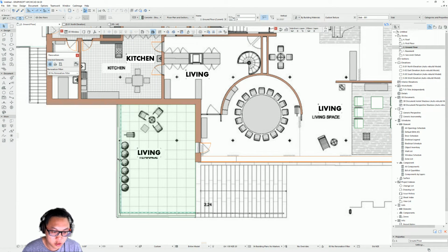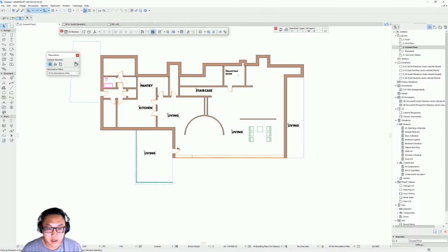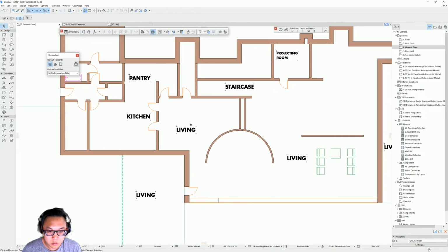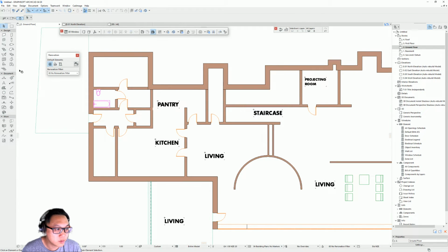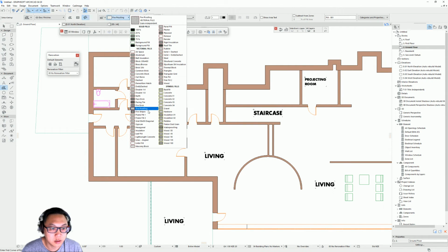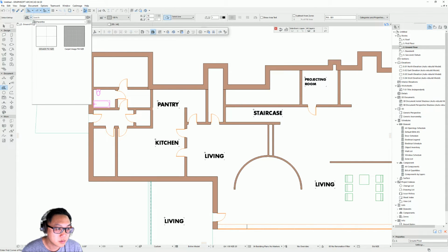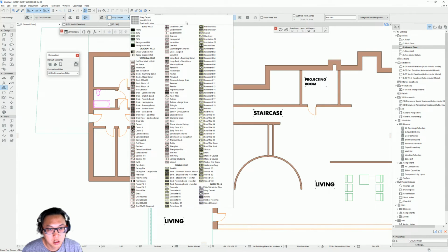Oh, let's say you want to put some tiles here, because if you turn off this layer, it's kind of there's nothing. You want to show some tiles, like on this one here. So you can either use a fillet tool and set an image. When you choose fillet, I think sometimes it goes automatically on this one, but if you go on this here, it will give you more options on the patterns that's on the fillet.